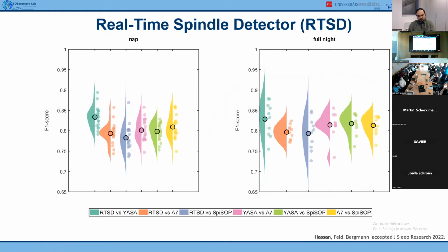So before we actually went there, as I showed you earlier in the experiment design, we want to target the sleep spindle, and there was no good solution available in the market or in the research literature, no ready-made solution to detect the sleep spindles. So we built our own algorithm, which is called the real-time spindle detector. It depends only on the last 500 milliseconds of data.